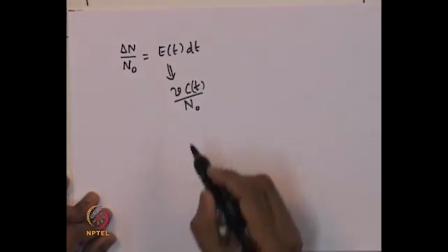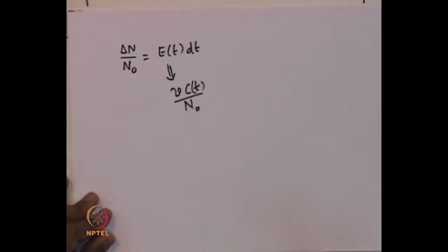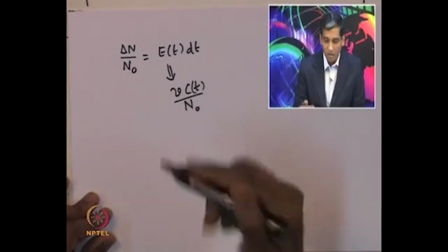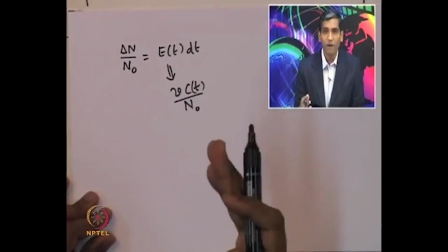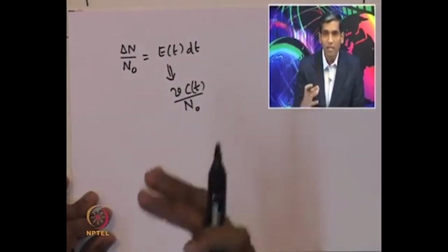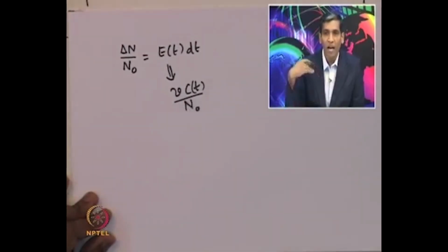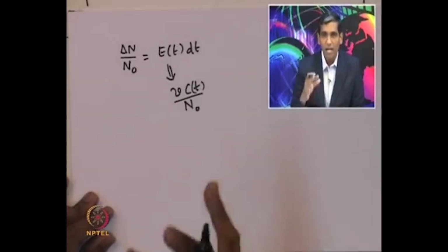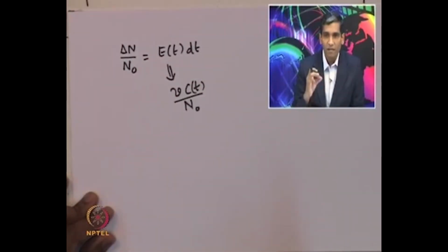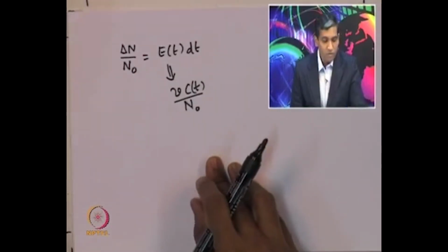What it represents is that it basically describes how much time different fluid elements have actually spent in the reactor. So, this quantity E of t, which is the residence time distribution function, quantifies how much time different fluid elements have resided inside the reactor before they leave the reactor. That is an important property of the vessel, which is captured in this residence time distribution function. So, what can we do with this?